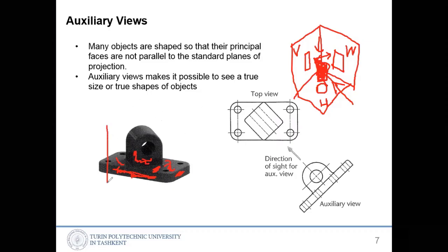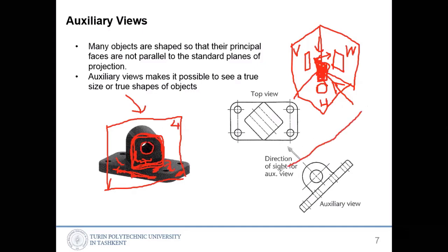So that's why we are making an auxiliary plane. This is plane 3. We are making a 4th plane, plane number 4, parallel to this side, and then we are projecting everything to this plane to see this side as is, like the original view, the true view. Okay, so same, we are making a plane. We are watching from the top to this. When you see from the top, you will see this kind of thing. And also this side, you will see as a line.